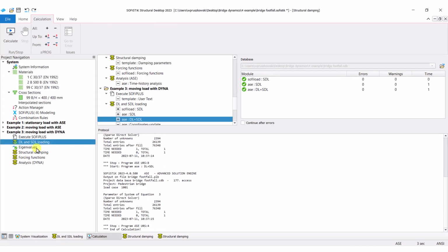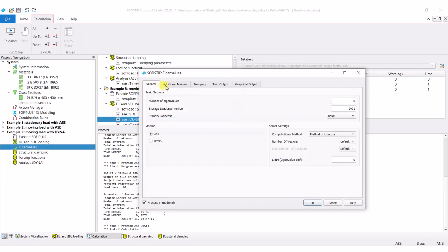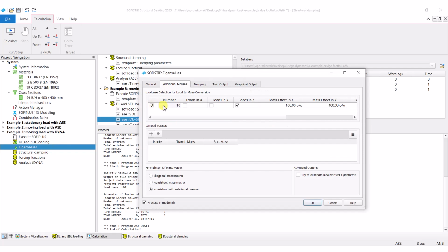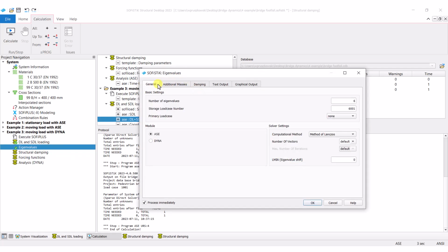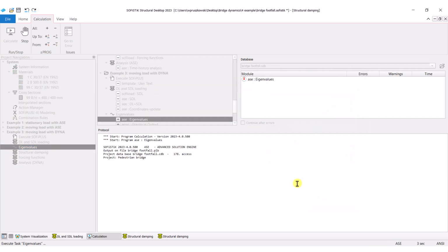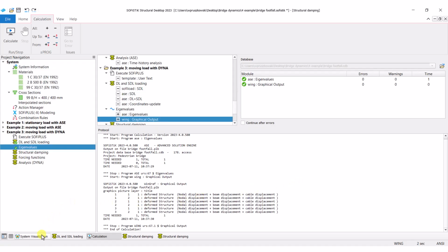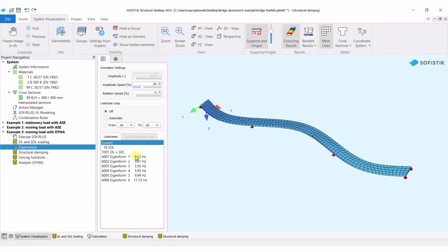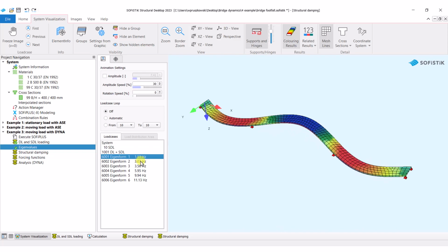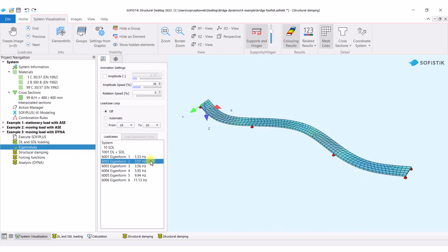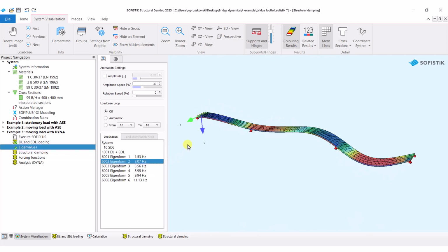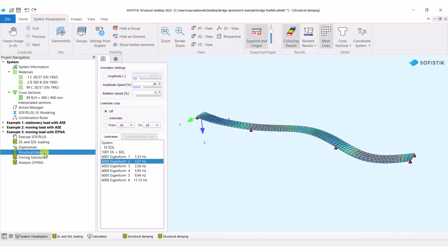And let's move over to the model analysis. We do have to remember about keeping the load case number 10 as additional mass. Let's execute, and let's review the results. So the natural frequencies of the structure have obviously changed due to changes in the geometry itself. But the first and second harmonic of our structure are still the relevant ones for the vertical loading. So let's treat natural frequency number 1 and 2 as our boundary frequencies for structural damping calculation.